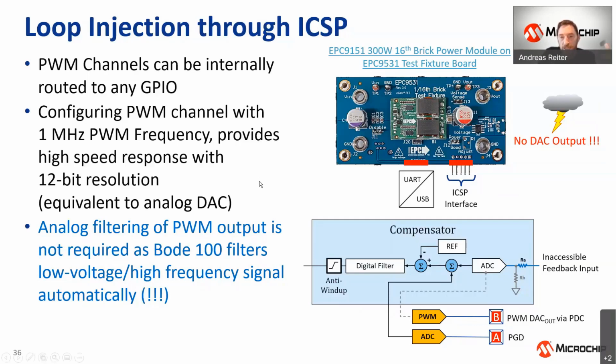So what is required in any case, before you perform the loop measurement, is to shortcut whatever you see at the input directly onto the DAC output, and then run a simple calibration measurement, where you can see that the gain and phase run flat, and at some point they start to erode. Then you use this data to compensate the phase and gain error you see in your final measurement.